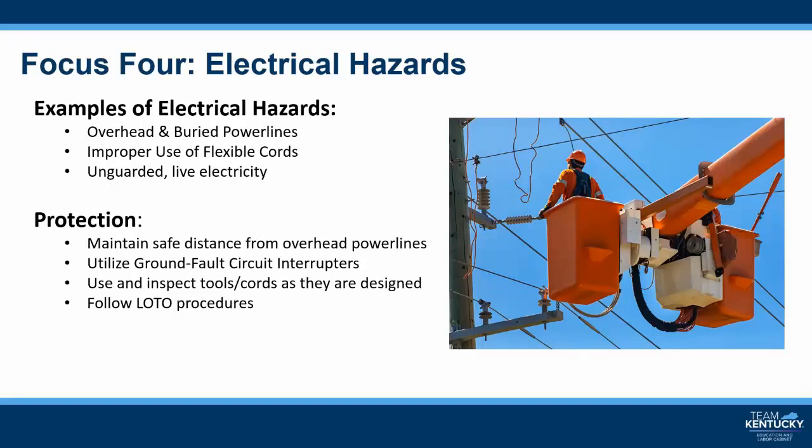The major hazards regarding contact with energized sources are electrical shock and burns. Electrical shock occurs when the body becomes part of the electrical circuit, either when an individual comes in contact with both wires of an electrical circuit, one wire of an energized circuit and the ground, or a metallic part that has become energized by contact with an electrical conductor. The severity and effects of an electrical shock depend on a number of factors, such as the pathway through the body, the amount of current, the length of time of the exposure, and whether the skin is wet or dry.